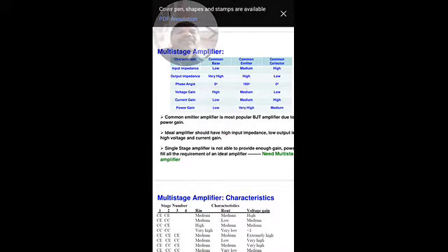So coming to output impedance, which is opposite to that of input impedance. The output impedance is very low in the common collector, but in common base, we have very low input impedance and very high output impedance. So that is the difference we have to observe in the two transistor amplifiers, common base and common collector.